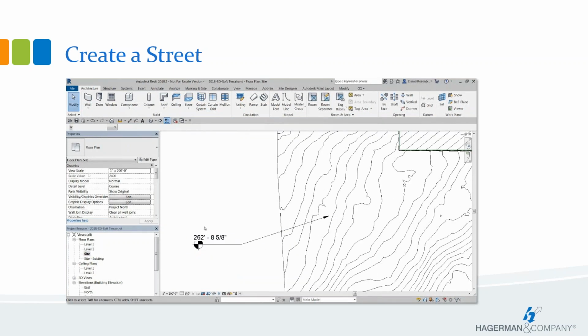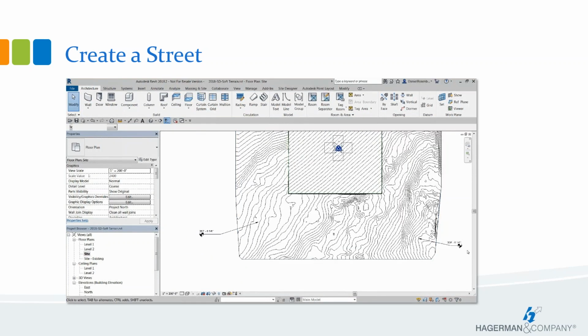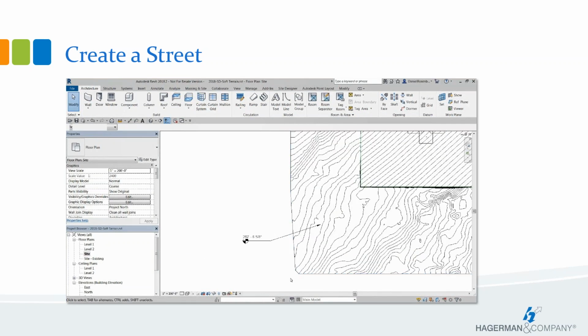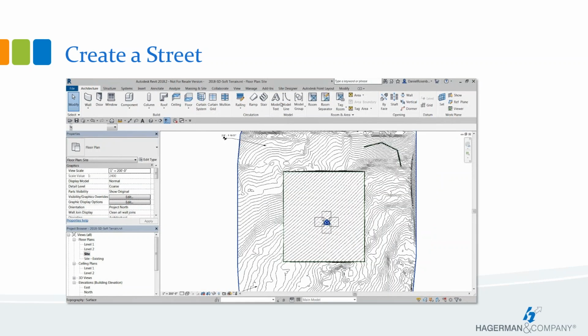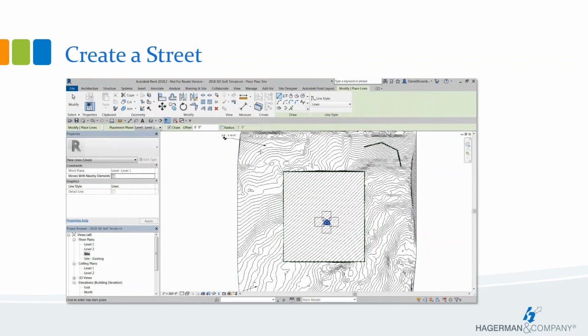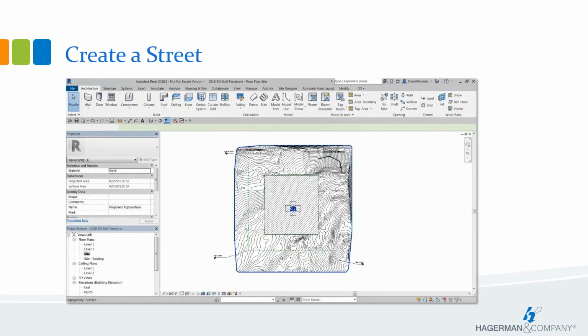The next thing I do is draw in some model lines. And I can probably speed this process up a bit. Once those are drawn in, I just drew in 2 segments and used the fillet tool to get a nice curve here.